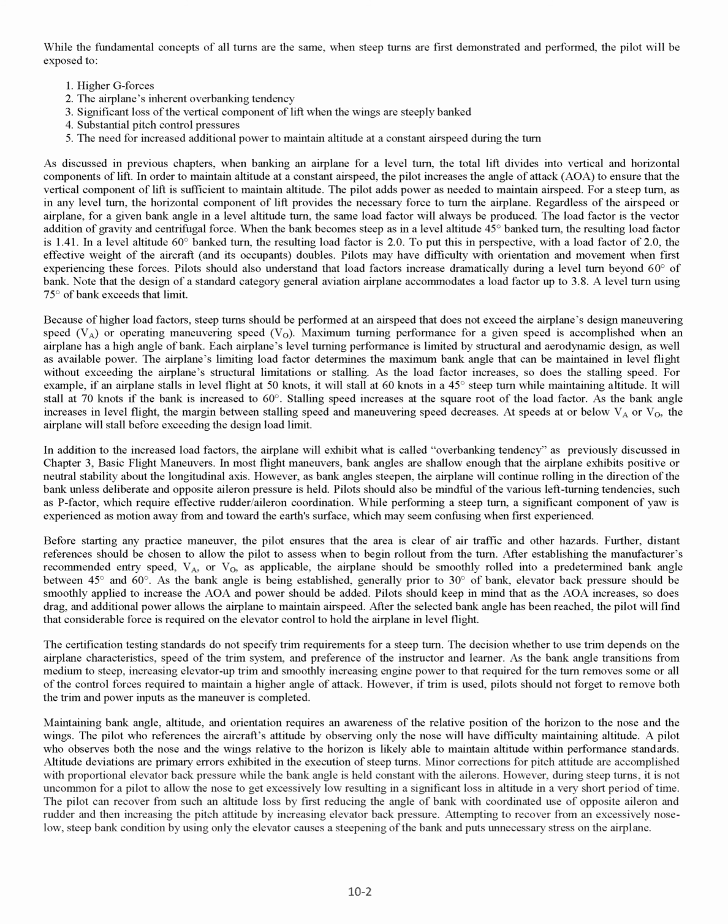As the load factor increases, so does the stalling speed. For example, if an airplane stalls in level flight at 50 knots, it will stall at 60 knots in a 45 degrees steep turn while maintaining altitude. It will stall at 70 knots if the bank is increased to 60 degrees. Stalling speed increases at the square root of the load factor.